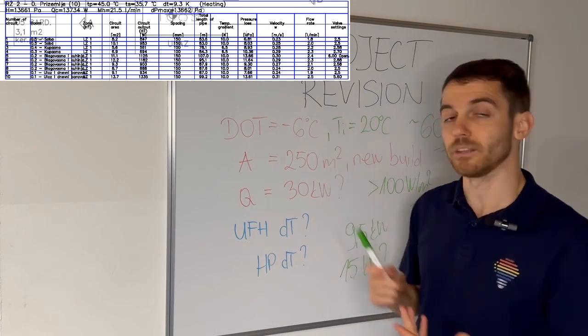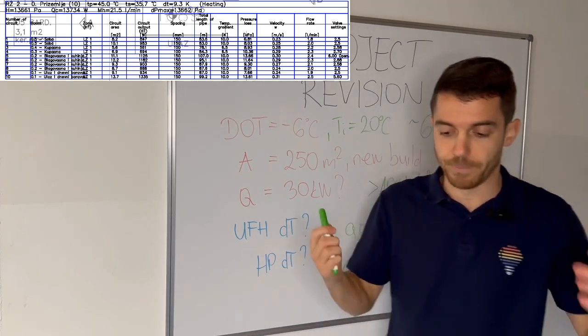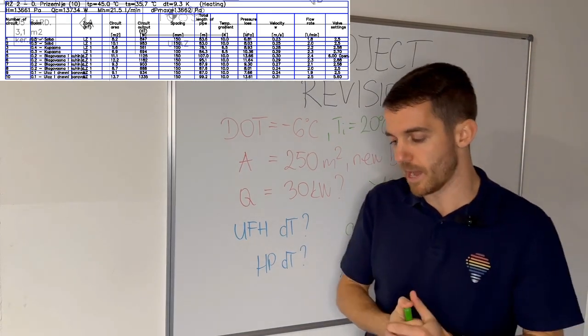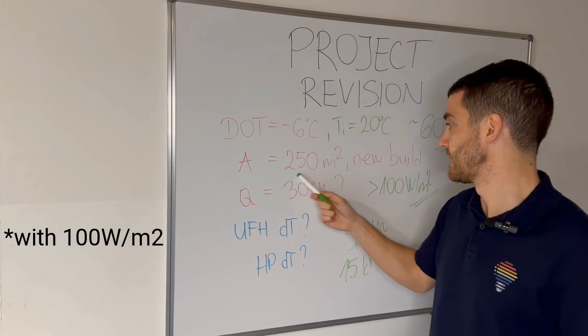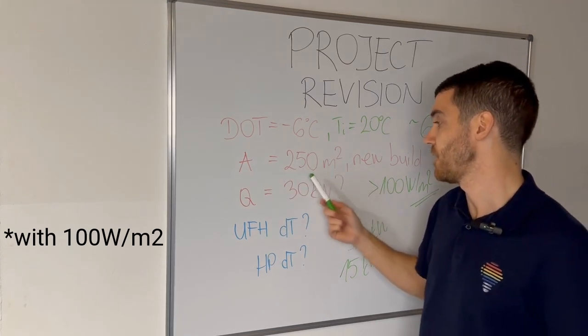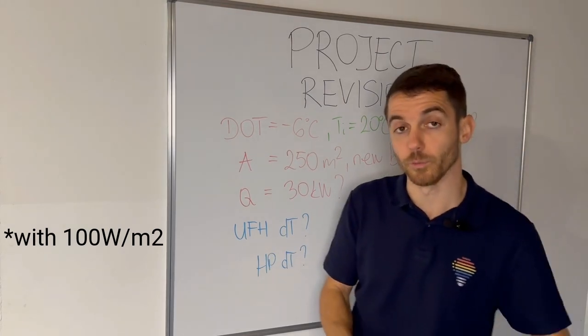This is related to this one because in this project, underfloor heating was calculated with some bigger delta T, with some strange numbers, strange areas, because for this surface of the house, probably you cannot have underfloor heating because the temperature of the floor will be too hot.